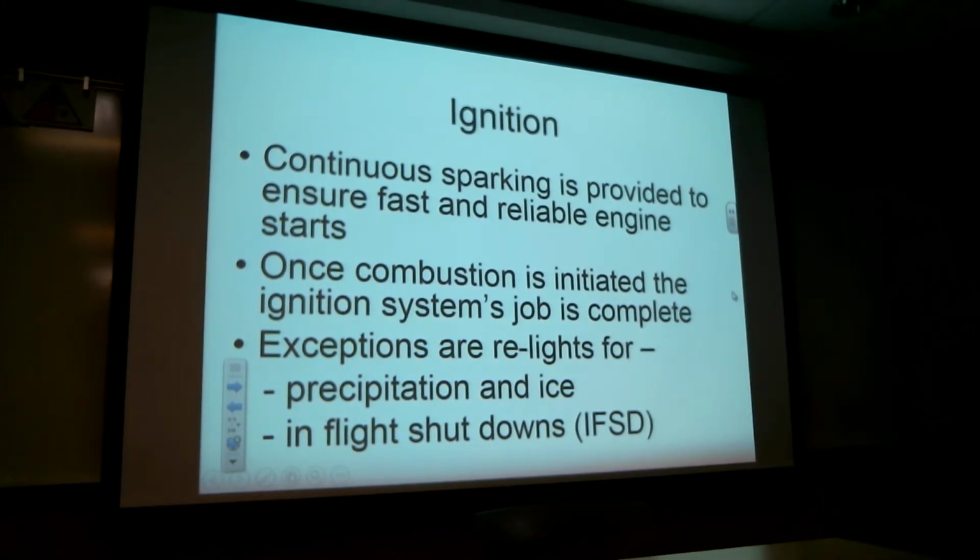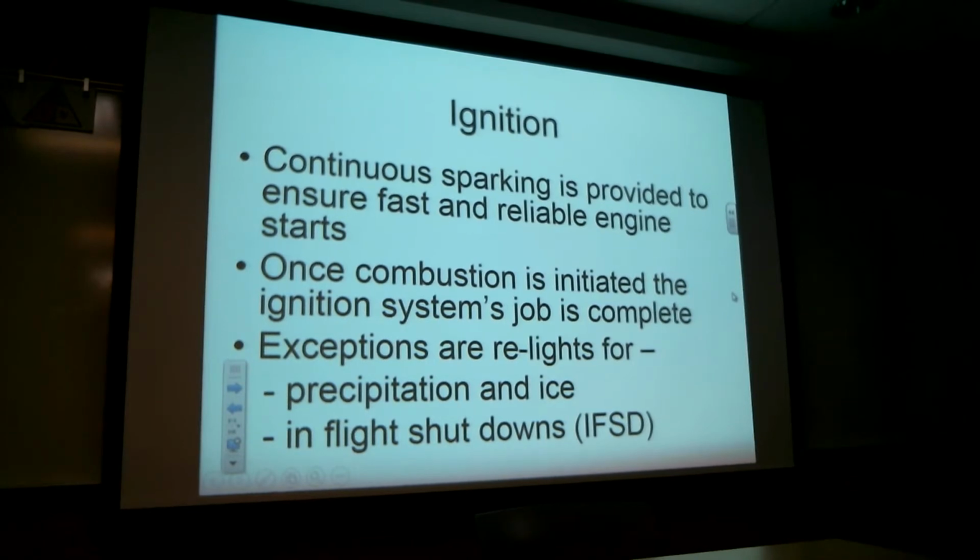It'll take some life out of the spark plug, but you have a choice between landing the airplane or worrying about a $100 spark plug. Okay, for restarts, precip and ice, maybe even, because the air routes carry airplanes a lot further than they used to, flight through volcanic ash.